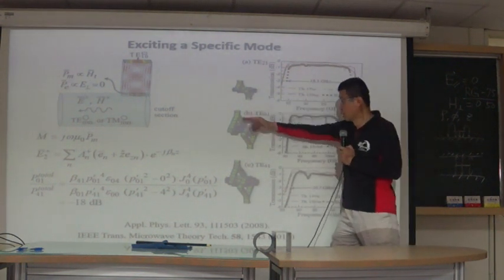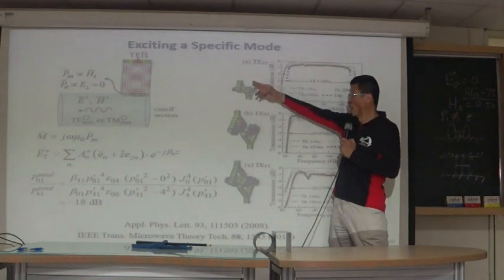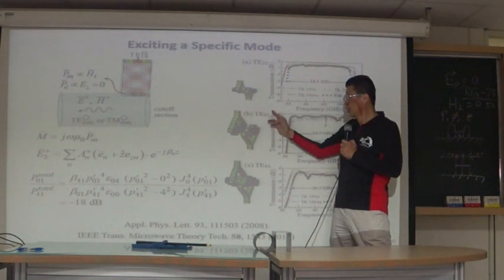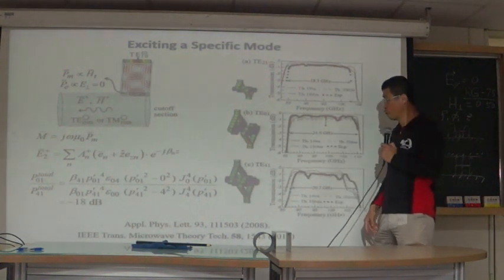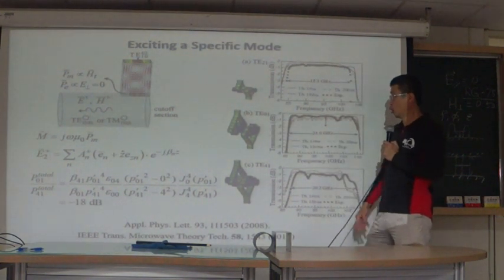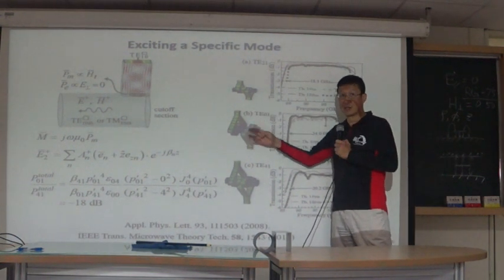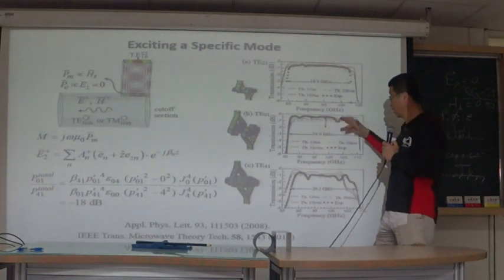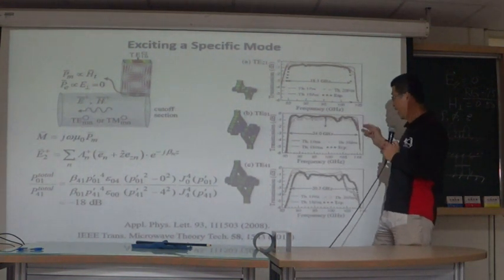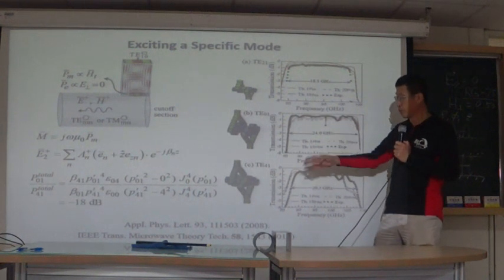It's a new idea. It excites the TE21 cylindrical waveguide mode, TE01 and TE41. No one excited these modes with high conversion efficiency. We have the world record, and we had the widest bandwidth 10 years ago.